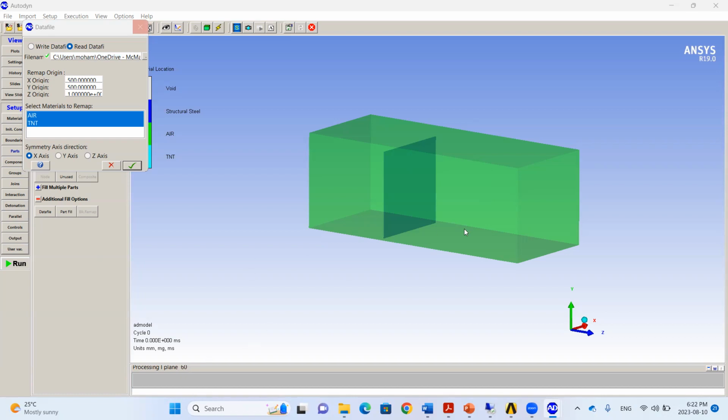Until filling is complete, we can speak about boundary conditions. Now we are inserting our explosive material in the middle or at the specific coordinate as we intend to simulate. And we expect that it will flow out through the air domain, but it will be reflected in the ground, in the base plane. So when we make our boundaries, we will make flow out boundaries in all directions here and here and here and the other side here and here, but not the base plane, to allow reflection, which means proper